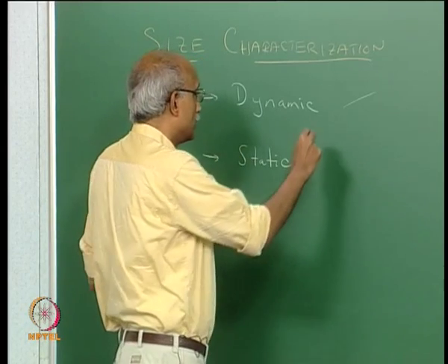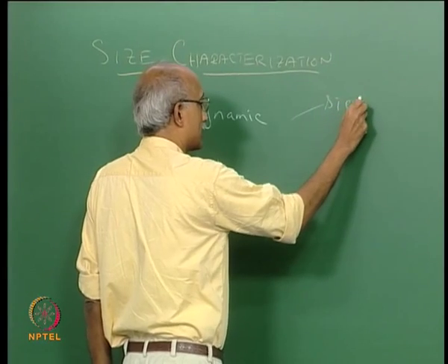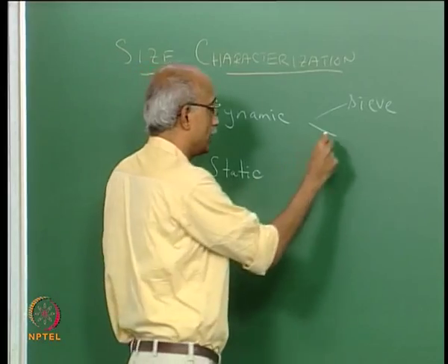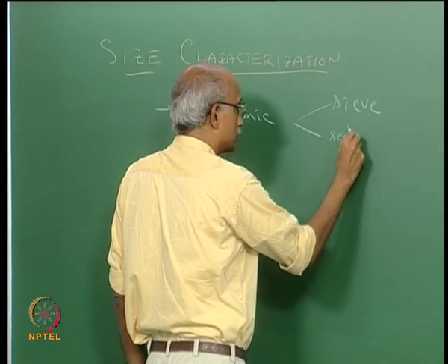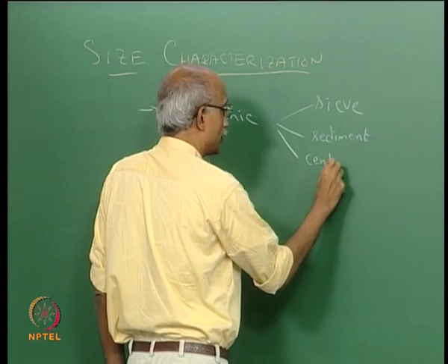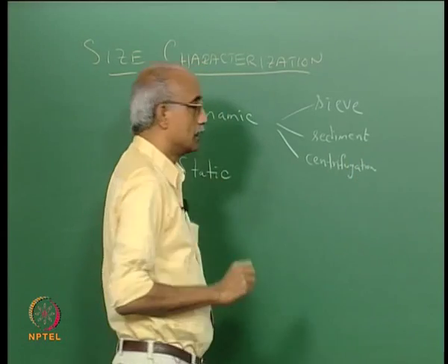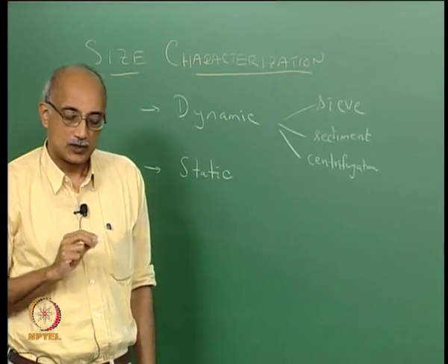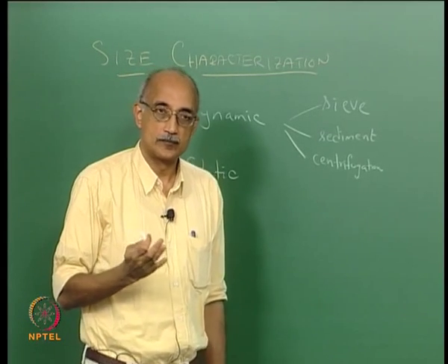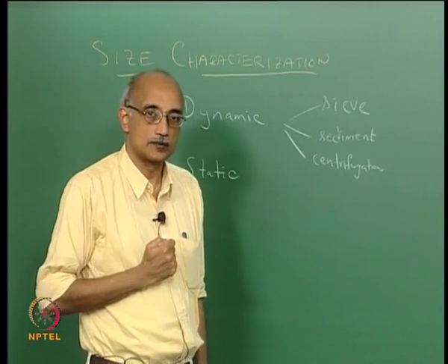So for example, if you are doing your dynamic size characterization by sieve analysis, or let us say by sedimentation or by centrifugation, in each of these cases the force that you use to set the particle in motion is very different, right? So, the size that you measure is also going to be relative to that force.